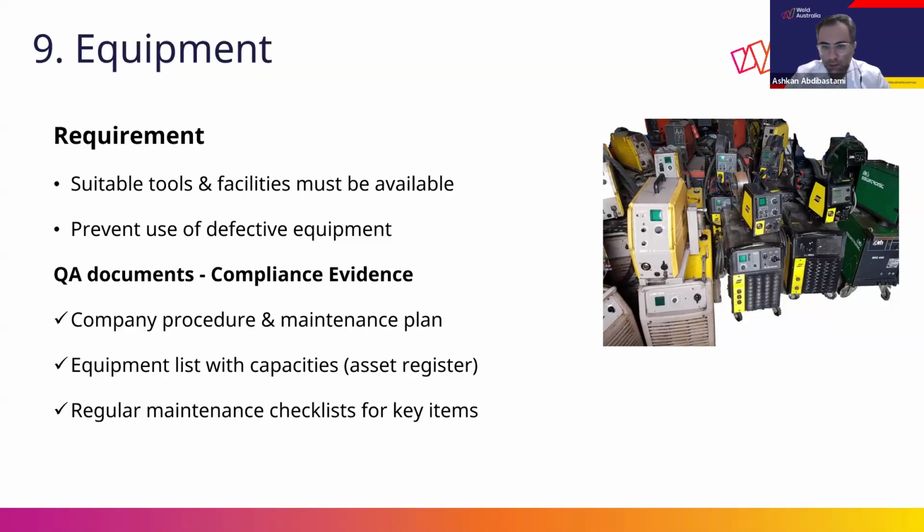If the product is structural steel, that's different. The inspector needs to know the details about steel structures, like AS 4100 for bridge design, AS 1554 parts 1, 2, 3, or 4, 5, and even 6 for stainless steel for the welding standards, and how he can interpret the defects or, let's say, discontinuity during the inspection based on those requirements.